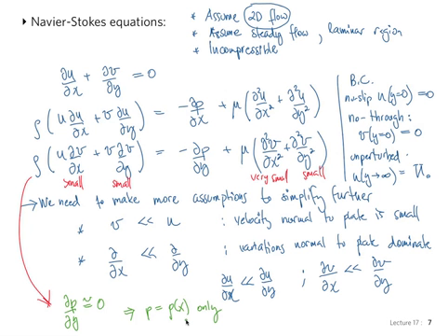So basically the y momentum equation can be neglected entirely now, and the pressure can vary only along the boundary layer. And in fact, one can consider the pressure to vary like in the inviscid unperturbed flow, since it doesn't vary in the y direction, and within a certain distance of the plate, outside of the boundary layer, the fluid is inviscid, then the inviscid pressure applies.